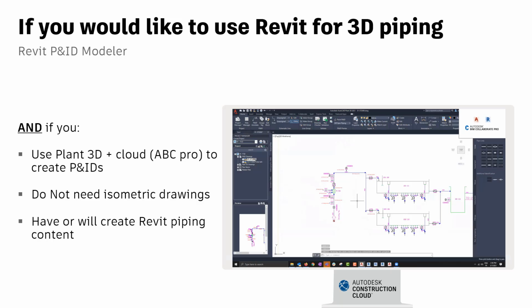If you don't need isometric drawings, because Revit cannot, as is, generate isometric drawings. There are external plugins, but as a standalone product, it cannot generate isometric drawings. And also, if you are willing to either use your existing Revit piping content or are willing to create some Revit piping content, which is not as rich as the Plant default piping content.